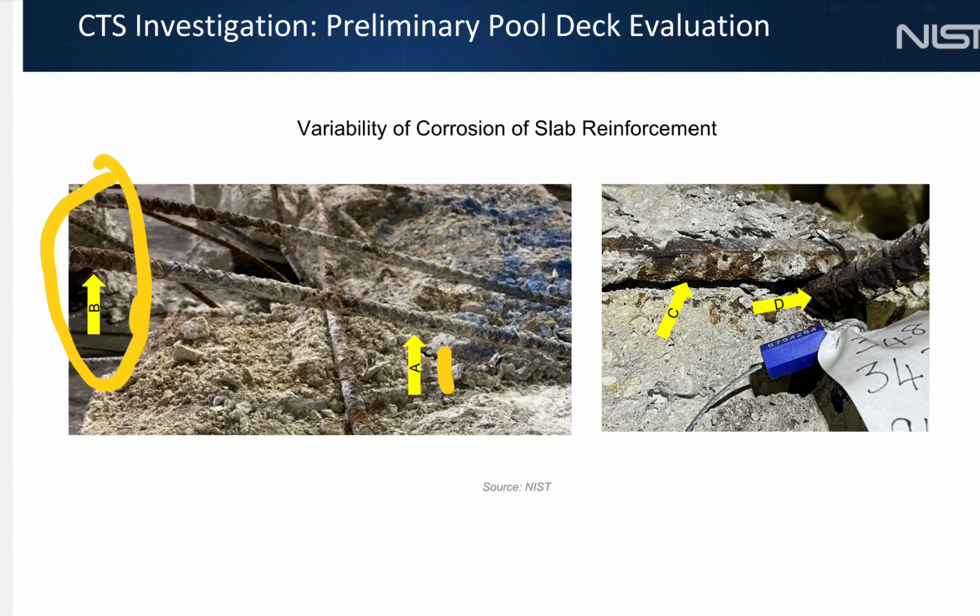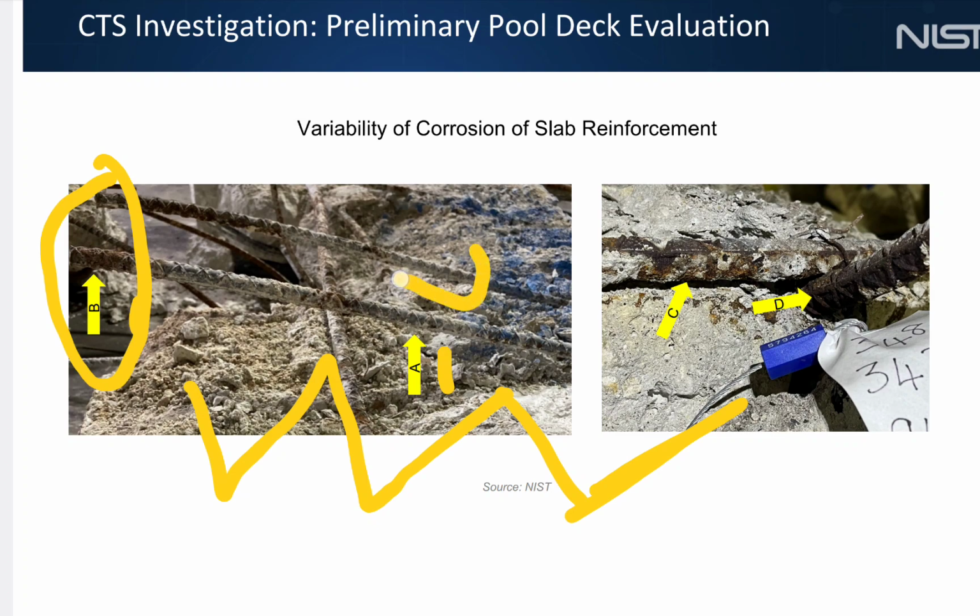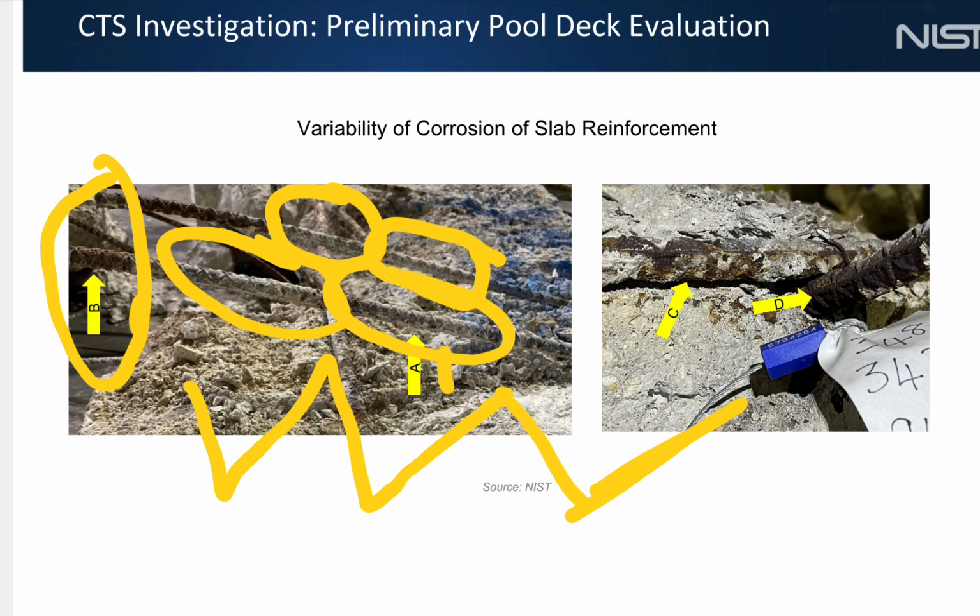Well, look, the deformation is what matters. The deformation of the steel. Does it still present as like new? Because rust can be present on reinforcement, and it's legit. It can still help, if anything, increase grip force. What this tells you, though, is the paste was here. See the whiteness? The white is there. So that means it had a grip force of paste.